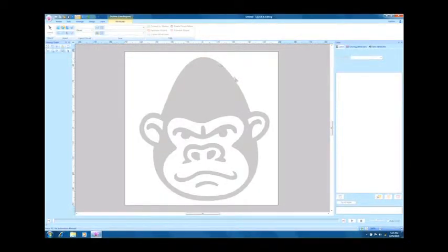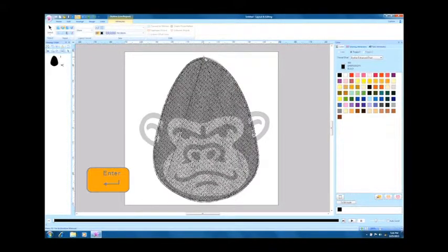Region Sewing Part 1 Head. Click points along the outline of the head. Take care not to overlap points or cross any lines. Once you have outlined the region and return to your starting point, press Enter to finish your entry.